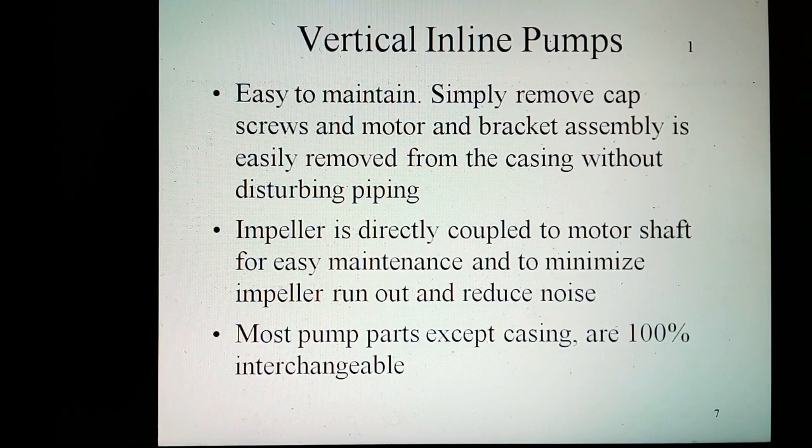Simply remove the cap screws and the motor and bracket assembly is easily removed from the casing without disturbing the piping. The impeller is direct coupled to the motor shaft for easy maintenance, to minimize impeller wear and reduce noise. Most pump parts, except for the casing, are 100% interchangeable. The inline casing has provisions for mounting an optional support base should the pump sit on the floor.